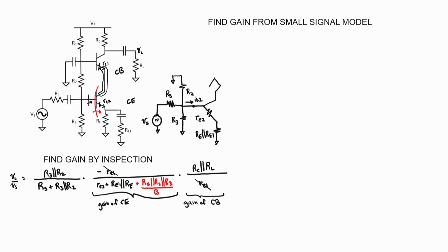Transistor 2 acts like a current source at its collector, and it provides a current of beta times IB2. And now we find ourselves at the emitter of transistor 1. Let's draw the little emitter resistance RE1. The base is attached to an AC ground, but we still have base current IB1 flowing into the transistor. The transistor derives a collector current of IB1 times beta, and it pulls those through two resistors, RC and RL. We have up here our output voltage, VL.